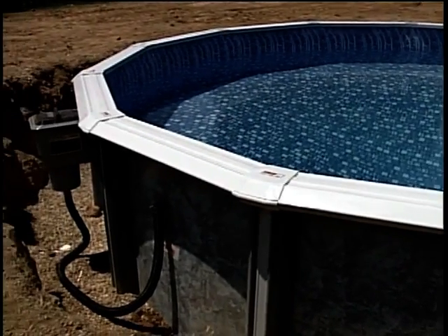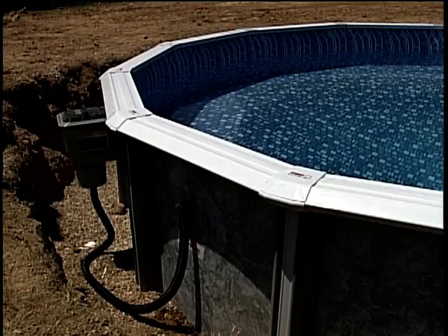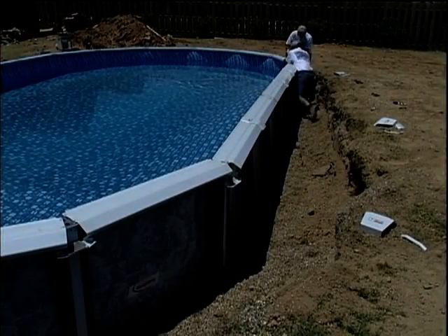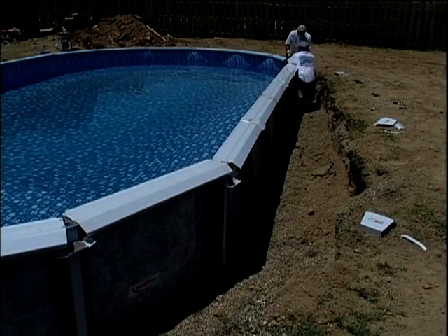Also at this time, consider the groundwater and water table issues you may have in the area you are working. Groundwater can be a serious problem for your pool if not allowed to drain properly. There are a number of ways to do this. We suggest installing a drainage pipe around the outside of the pool at the base. Run the pipe to an area away from the pool that will allow any groundwater pressure to be released away from the pool.